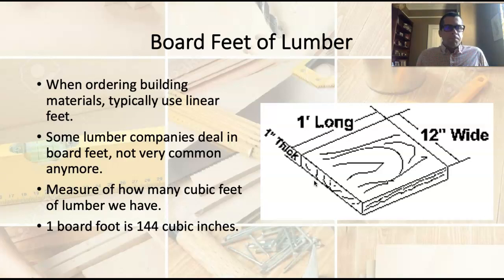We can talk more about this in the future, but the only place that you're really going to encounter board feet of lumber is at Almquist. Schmidbauer deals sometimes in 1,000 board feet, and you'll look at your receipt and it'll say like $783 for one stud. But that's actually giving you the price per 1,000 board feet, and it'll say MBF, M standing for 1,000, like millennium.